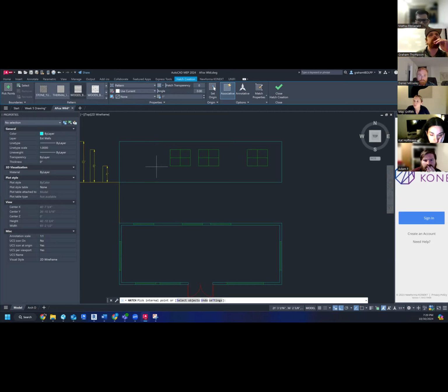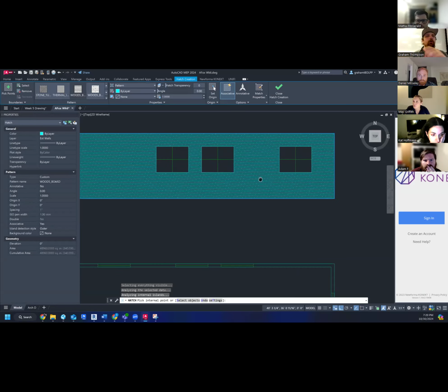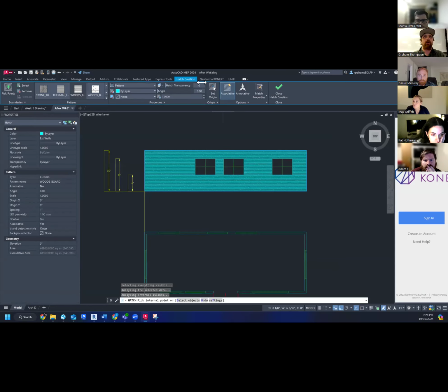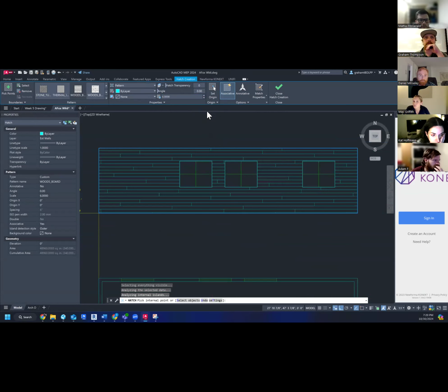Here, let's do that. I'll put some wood boards on it. Now, those look like they're really, really small compared to how big I want it. So I could change this hatch size right here to maybe twice that size, or maybe I want it 4 times that size. No. Yeah, that looks about good. Maybe I want it 6 times the size.